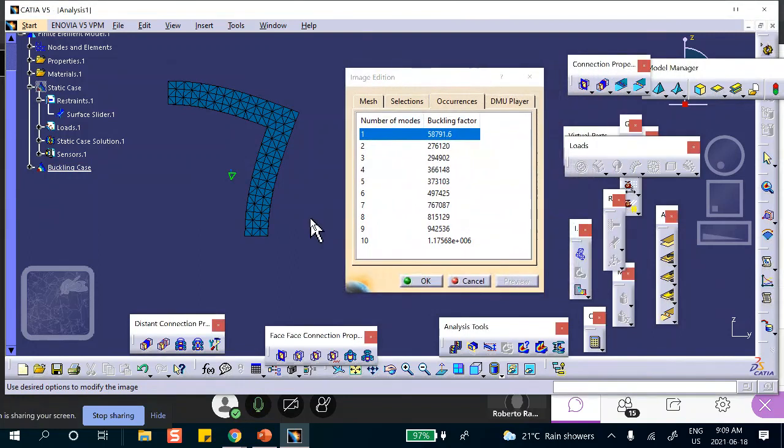Okay. So to get this mode, here's what happens. You need to apply this by a dummy force of 1. So it's that much, okay? However, that is only for the side that is facing you. There is also a back side that you did not model. So you're going to have to multiply this by 2, because this will only give you the buckling load for the front piece that you modeled. Remember, you split that thing into 2 halves. You didn't do the back one. So you have to multiply this by 2.